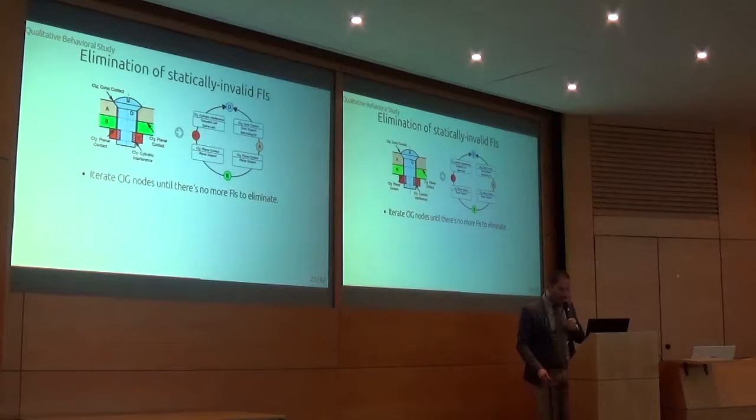Now, the idea is to iterate over the DMU components as the nodes of the conventional interface graph, and for each component, assess its compliance with reference state 1 and eliminate functional interfaces that do not abide by this reference state.